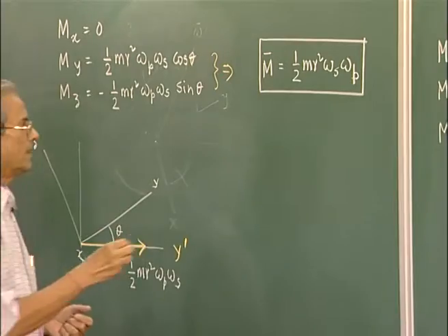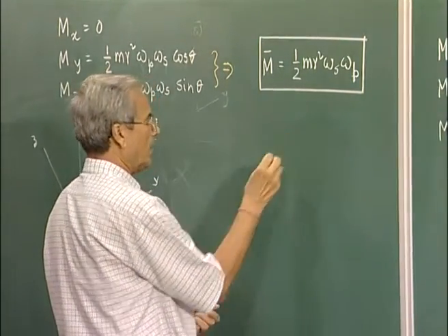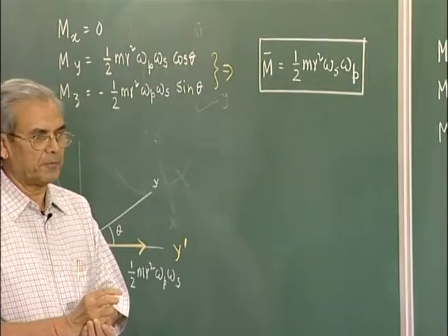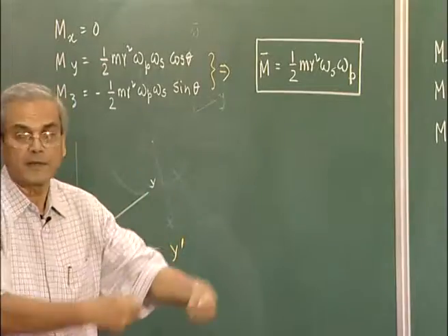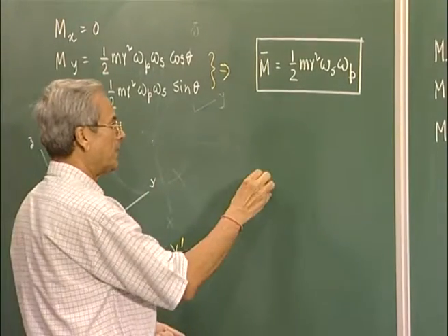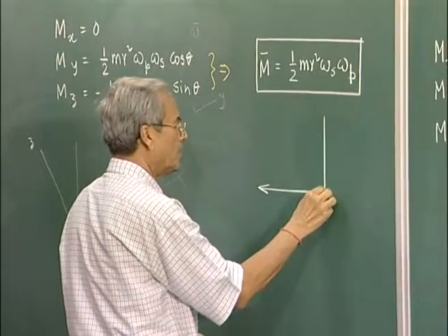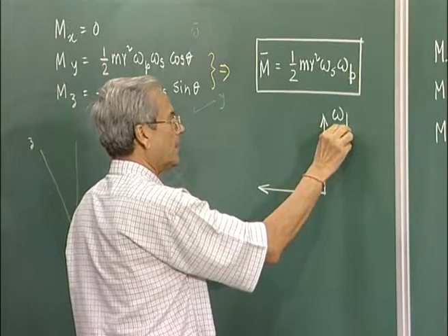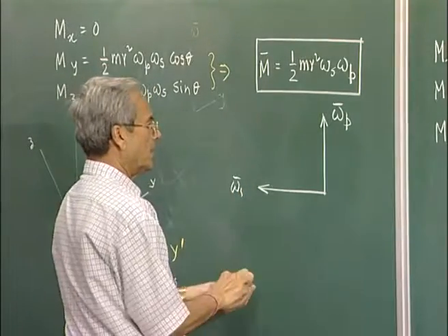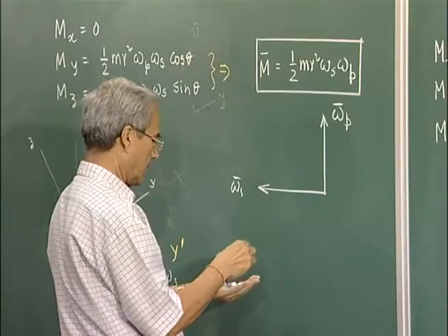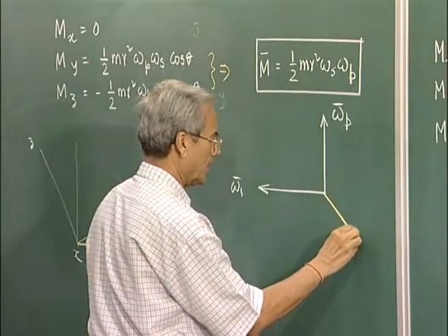So, you see, it is something counterintuitive when you consider our dynamics of planar system, where you apply a moment, the thing tries to accelerate in the same direction. Here what is happening, the body is spinning like this, you are trying to rotate about this. You do not have to apply moment in this direction, moment which you will have to apply will be in this direction.